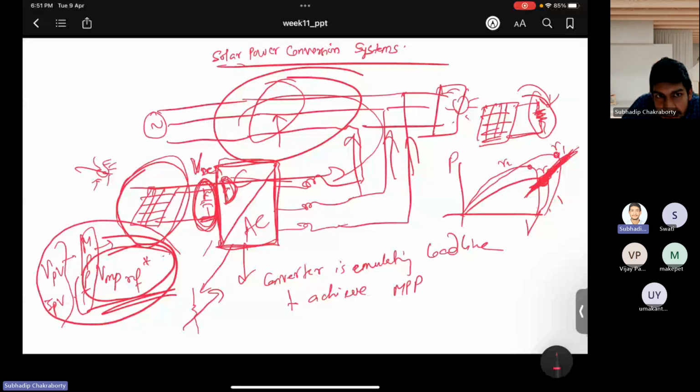So it is very important that you interface these renewable conversion sources using the converter, and you utilize these converters to also provide harmonic compensation for the loads, such that you don't incur grid penalties. You must know that for rooftop arrangements of the consumers, you push power to the grid. You must know the net metering and all those things. You push power to the grid, but you should not push it at non-unity power factor.